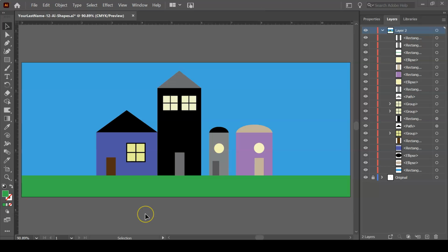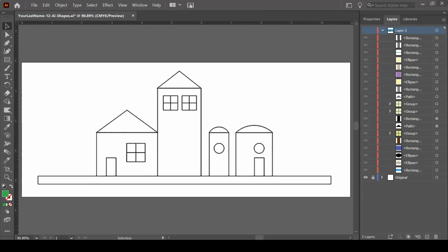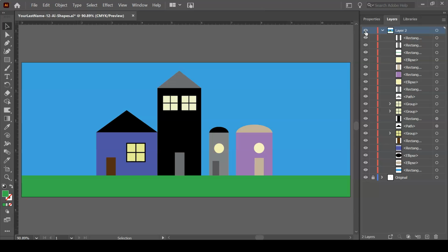This Illustrator tutorial explores using basic shape tools, fill and stroke colors, and creating vector files. We'll use the Artboard Tool, Rectangle Tool, Ellipse Tool, Line Segment Tool, the Pen Tool, talk about the Arrange commands, and layers. We'll start by placing this JPEG image of buildings into our Illustrator document, and then we'll use basic shapes to trace over that JPEG to create vectors.